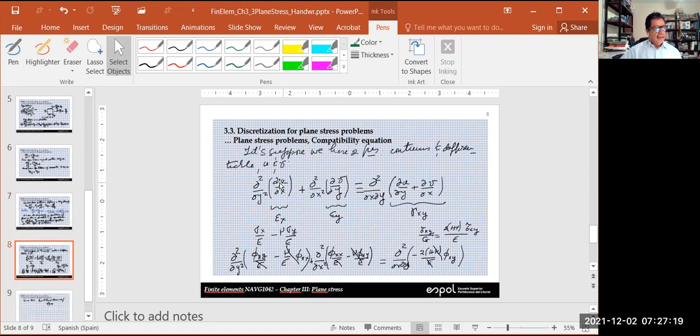So if we start by du dx and dv dy, and we assume that u and v are functions which can be differentiated without any problem, are continuous without any problem. And that's what we expect for the displacements in a plate, right? And we differentiate this twice with respect to y, this twice with respect to x. We can express this result in this way. And to go from the left to the right, what we need to be certain is that we can change the order of differentiation. And we can do that simply by saying that u and v are differentiable and also continuous. You can remember that from your calculus of several variables.